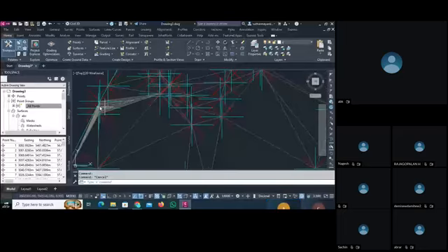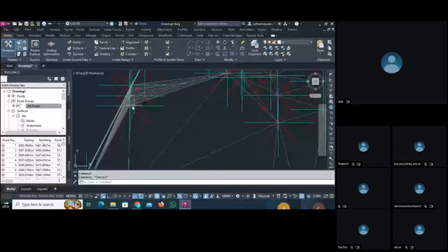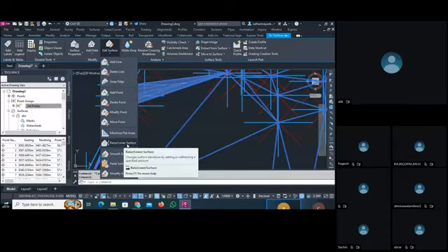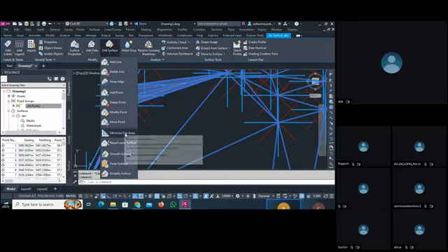Now how can we set our elevation here? We select our surface, we go into edit surface. Now you know how to add the line, how to delete the line. This is the region lower surface. If you want to raise your whole surface by 5 meter, you select this and give plus 5 meter, and your whole surface goes up 5 meter. And if you give minus 5 meter, the whole surface goes down 5 meter. So this whole thing we covered yesterday. So now I just want to focus on this point.